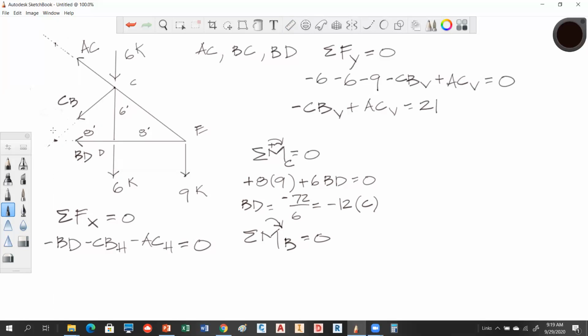Yeah. All right. Now this is kind of the tricky part of this whole process. Let me put this back. Up here, this is actually point A. There's going to be two vectors associated with this. One going that way, and one going that way. So this turns out to be AC vert, and this turns out to be AC horizontal. What I'm using here is transmissibility. Does everybody see that?